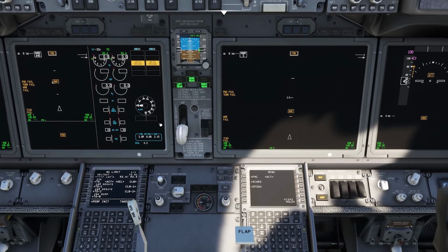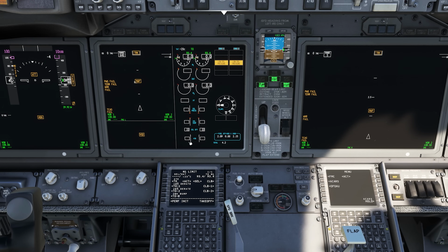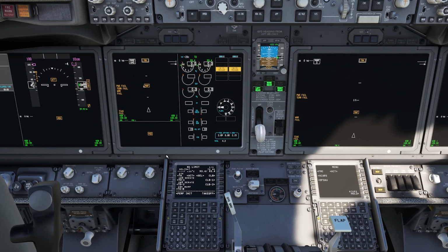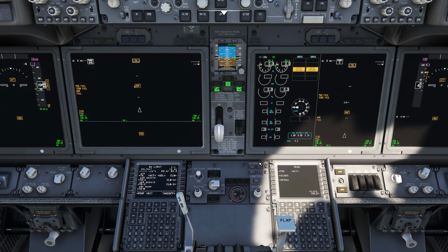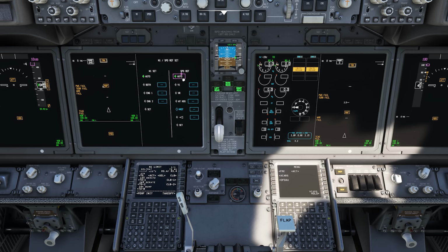Whilst we're on the topic of engine displays, the operator pilot flying has the engine indications on their closest inner DU. In this case it would be the captain pilot flying, and then we can switch this over. This would be the first officer pilot flying. We also have no lower DU, so a lot of the indications that were here were moved down. The autobrake is down here for the RTO, and if we want to set bugs in the FMC, we press this info button, and then we can manually set V speeds if we don't have an FMC, for example, your N1 thrust settings as well, your VREF and gross weight too, using the selector switches here.